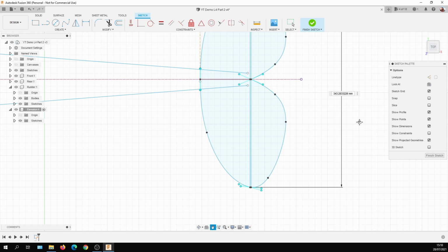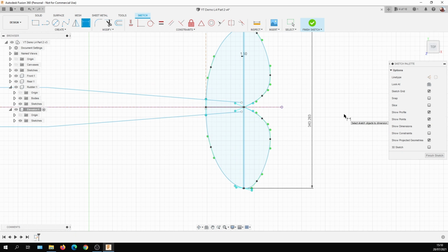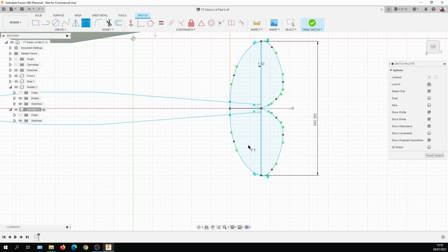So that's telling us our rudder's roughly about 350. So that gives you some idea. So I think what I'm going to do, I'm going to create the rudder and elevator out of balsa. Because one of the things I found on the flight test Bushwhacker was the rudder and the elevator did take quite a hammering, and most of it was through hanger rash, knocking it about, getting in and out of the car, off to the flying field.